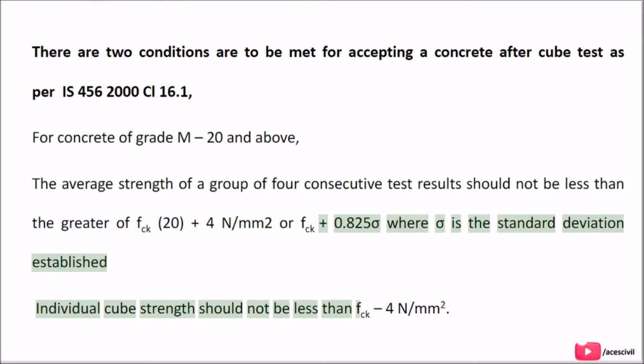Individual cube strength should not be less than fck - 4 N/mm2.